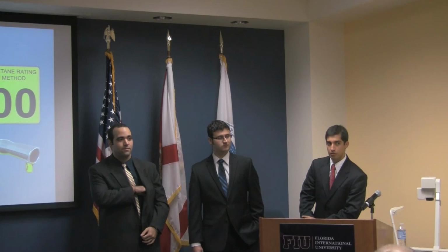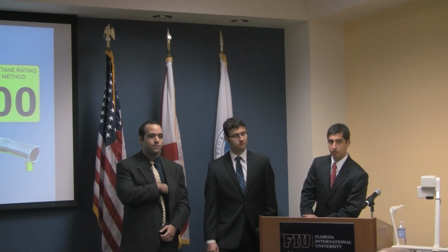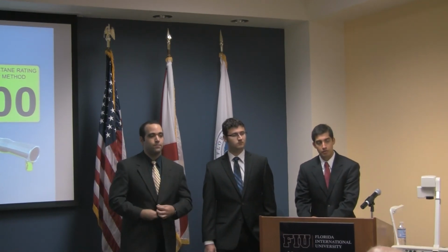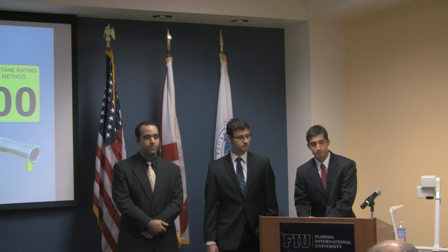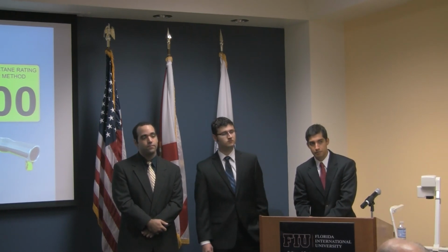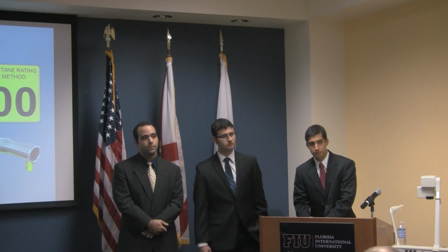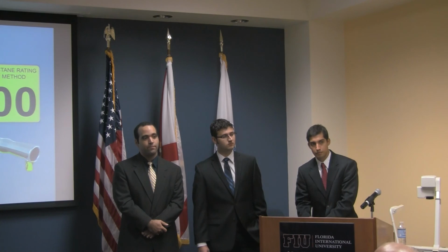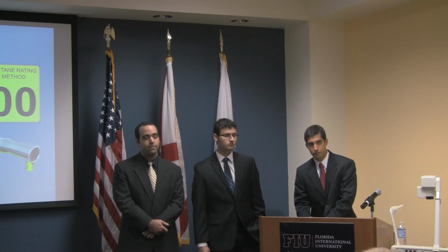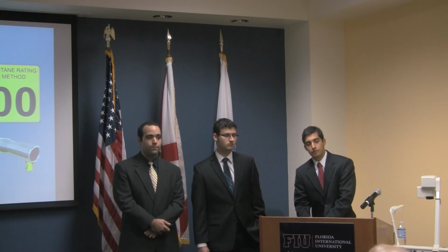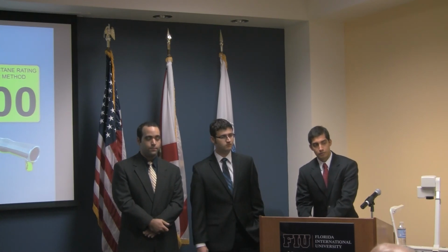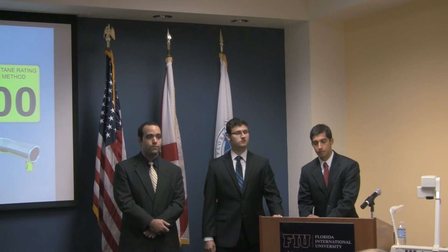Just a thought, because you said your limit is the size of your orifice. You're allowed to have a maximum. There's nothing to say you can't go a little bit less. Yes, you are restricting the engine, but if you put a supercharger or turbo on, I know you can't use nitrous, you're kind of compensating for that restriction to get more air in there. But that way, if you have to change fuels for whatever reason, your restriction allows you to do it.